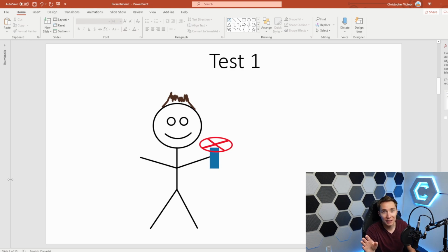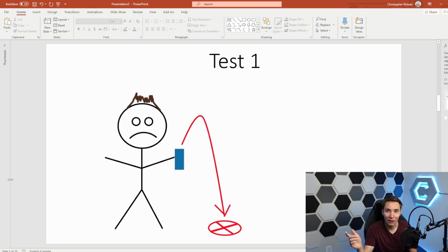So the first test started out fairly good, fairly hopeful. There was a young Chris with his die grinder and his spinner. Unfortunately, if you remember me talking about orientating the airfoil the correct way for the rotation, I didn't find out that until after the first test. And my top produced downforce instead of lift. Instead of a helicopter blade, it was just a top. We went back to the drawing board and flipped around the airfoil.